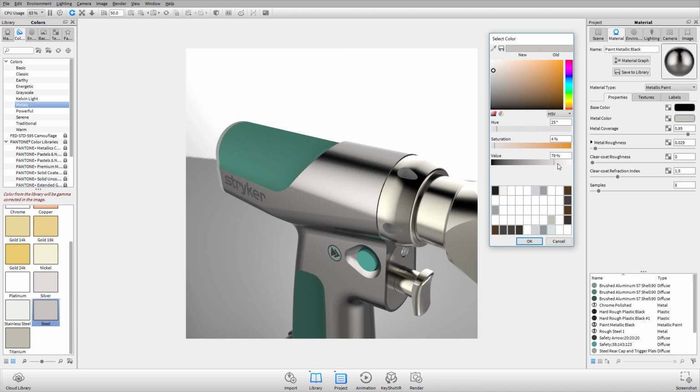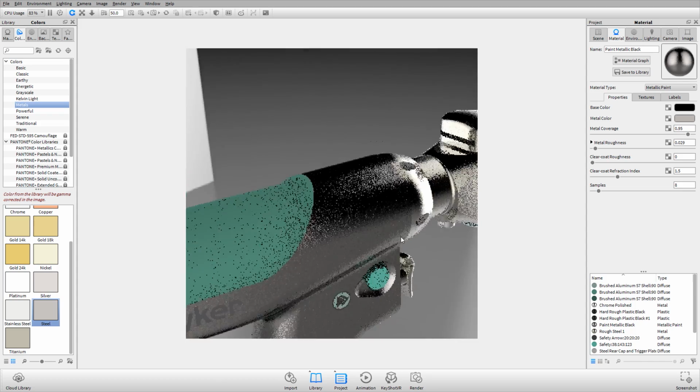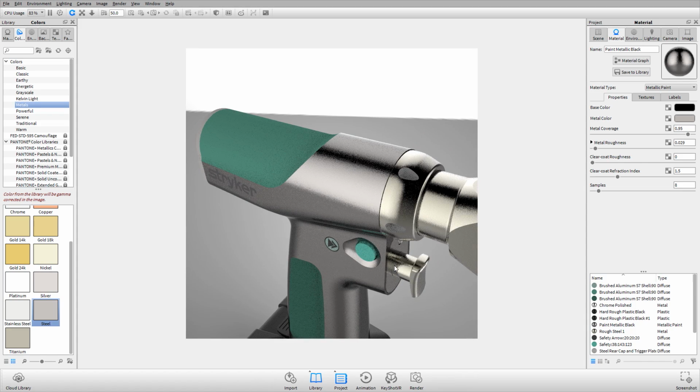So if we want to see more light reflecting off our material, increase the value, make it brighter. You can see here, now I'm blowing that material out. If you want to decrease the reflections on that material, I can back down on that value or darken it. What we're doing here is controlling the amount and the color of light that's reflecting off that material. That's what the specular component controls. So now if we decrease that, it's getting less blown out. Looks good. I just backed it down a little bit, but now I don't have that totally blown out material. It's a little bit softer, and I still get the right color and the right impression that I want. And then you can still go tweak the lighting on this one.